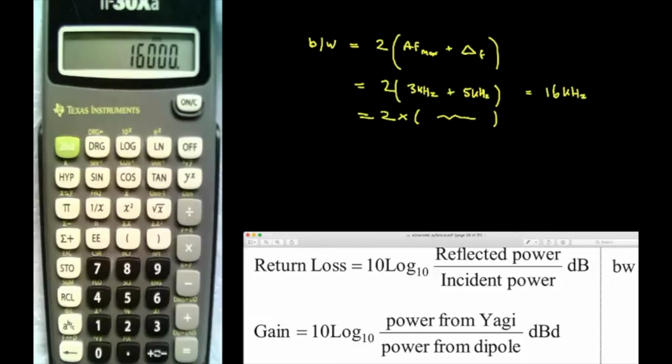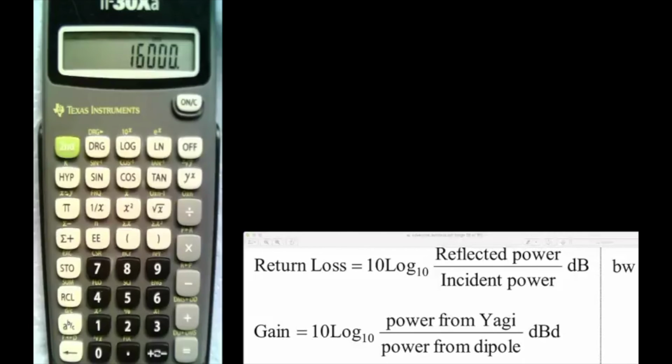So what you're saying here is that an isotropic radiator, which is the theoretical base radiator from which everything is derived, if you like, you can imagine it as being a point source in a translucent sphere, and you have your aerial in there instead. You have a half-wave dipole. You will illuminate, if you like, 2 areas, because you know the radiation pattern of a dipole is sort of like that, isn't it? There's the dipole, so it's got two lobes. So it would do that.